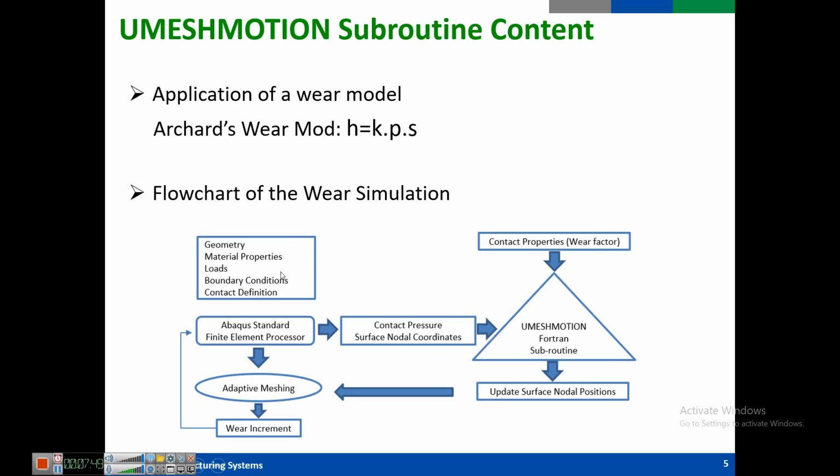In our model we usually provide geometry, material property, loads, boundary conditions, and contact definition. It's necessary to tell you that in Abaqus for wear simulation using UMESHMOTION, we usually use Abaqus Standard static.